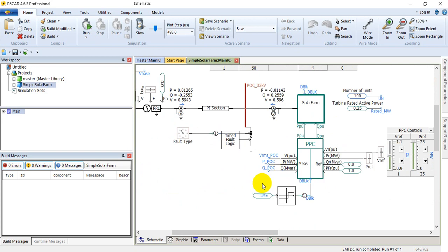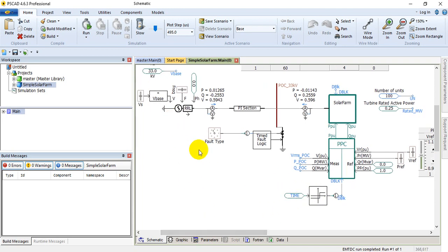Let's start with our first component, the power plant controller. In the power plant controller you can see that there are different inputs, different reference values, and a different output. At this point the first component is the delay block. The delay block means that the power plant controller will be in action once the solar has started, MPPT is in function, and the solar has reached its maximum steady state value.